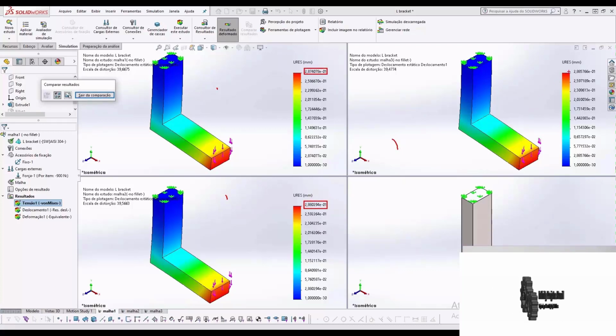Because as we refine even more, the displacement will converge. They will converge with each other toward the result. That's why, independent of whether the mesh is more refined to analyze displacement, the result is going to be the same. Okay, I don't have so much need for precision, so the differences are irrelevant, and if there really is a difference between them, beauty, now it's clear.